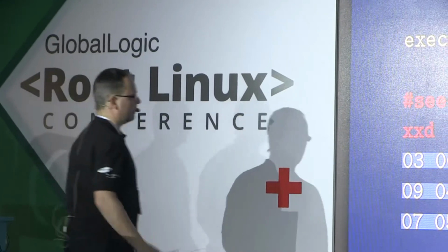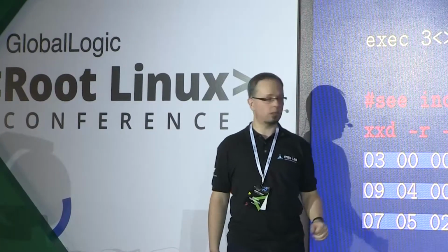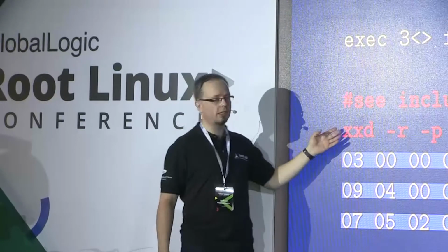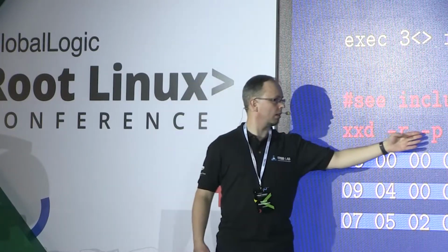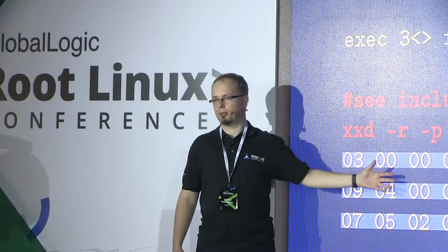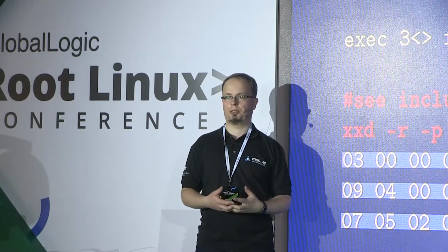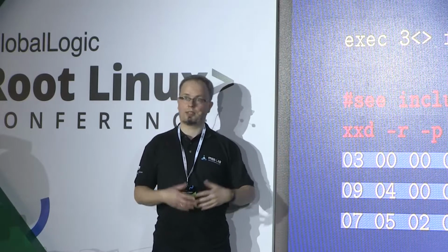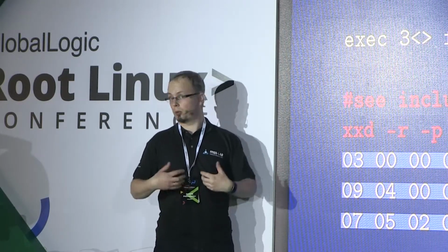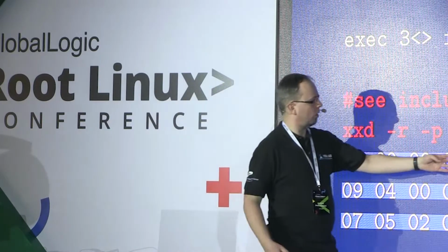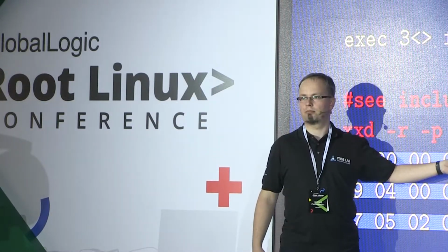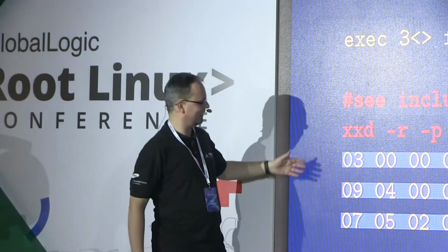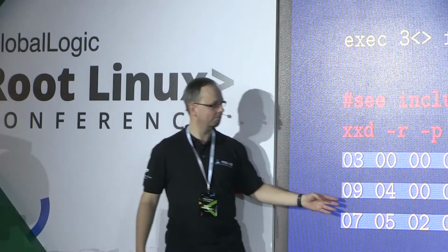Now we write USB descriptors to the EP0 file. So we redirect the output of some command to our EP0 file. The xxd command, given the -r and -p switches, takes a hex dump and creates a binary representation of it. So we write descriptors in binary form. The number 3 here says, as the name implies, we will be using the function.fs version 2 header. Now, how much in decimal is 27 hex? 39. And indeed, there are 39 bytes in this block.